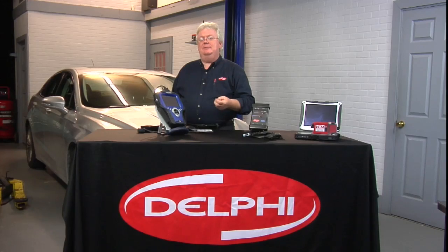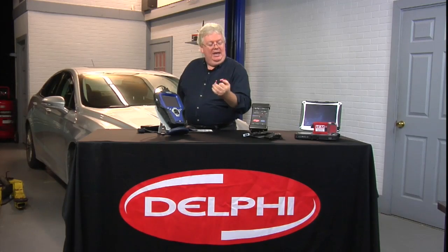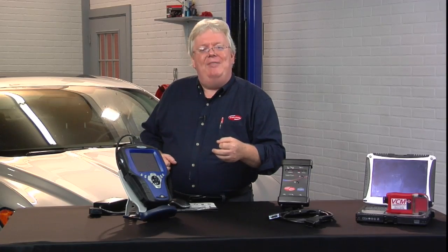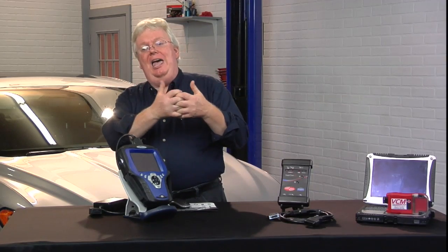And if you do fleet work in your garage, you've got a small fleet you're taking care of, you may see some 15, 16 models in your bay. You're an independent aftermarket shop. You don't do warranty work, you're not a dealer, but you're working on them anyways. And so you have to lie to your scanner, tell a little fib and say, hey, it's a 14, because that's as late as my scanner goes, for example. And that's when we have issues with maybe this PID is not reliable, not germane to what we're talking about. It exists, but it's not working. And the same thing would apply to the mode 6 data.